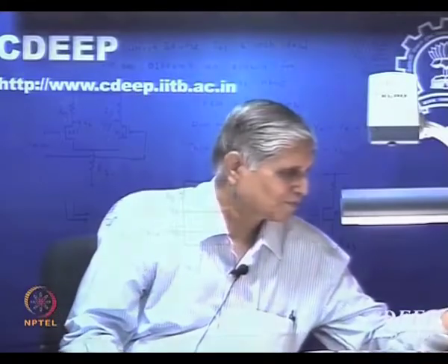Ideally the common mode rejection ratio is infinite, okay. What does that mean? No common signal will be transferred, only the difference signal will be amplified, is that clear? However, in reality if ACM is finite, the CMRR will not be infinite but maybe 10 to the power 3, 4 or something, 80 dB, 100 dB or 120 dB kinds, okay. Now we want to find, if ACM exists, what is the real value now.